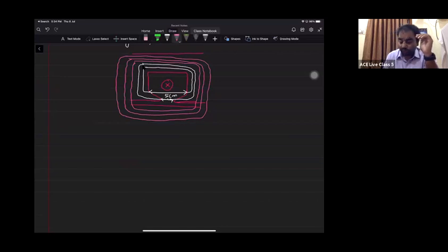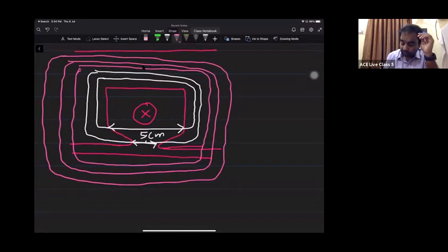Why? Because this length is 10 mm. Previously one flux line was traveling, definitely one. But as the slots are partially closed, when they are approaching the air gap, the length along that path is reduced. Then one more flux line will try to flow, and the remaining flux lines will take the other path, right? So can I say in semi-closed or partially closed slots, the leakages will be more compared to open slots, right? Is this point clear? Confirm me, all of you.